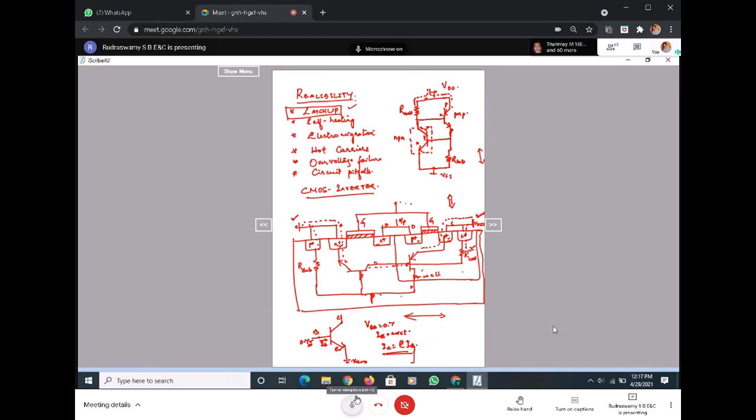What is your beta value? What is Amplification? Yeah, it's an amplifier. Beta is greater than 1. If I assume simply beta is equal to 10, if my IB is equal to 1 microamperes, my IC will be 10 microamperes. Is that okay?